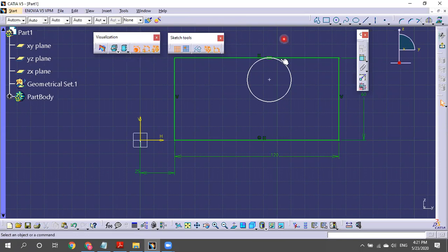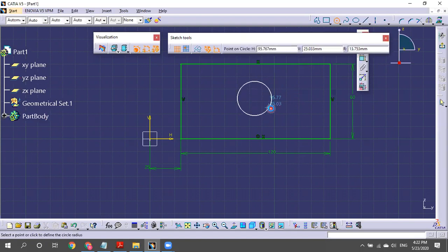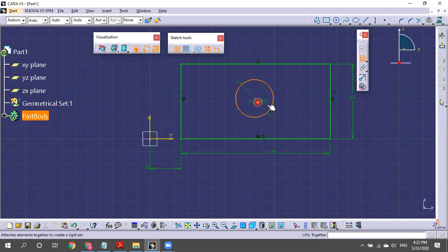Okay. Now I'm going to move these points, the circle. The circle will not come out of this until you delete this constraint. You can just select that and delete it with your mouse key. So now it is done, right? Now I can delete this point, anything. Now what we'll do is draw this and ensure this circle diameter is this much, and that this particular point is exactly coincident with this one.